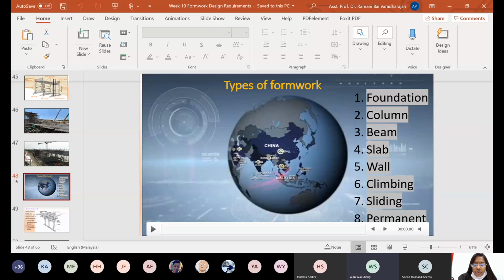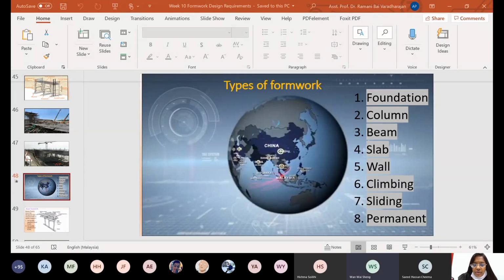Miss, what is the difference between the scaffolding versus the formwork? Between scaffolding and formwork? Formwork is mainly the sides and bottom, mostly the side and bottom is called form. The structure which is forming the column and beam or slab is called formwork. And if you are going to support it, the poles, the pillars, the piers that are going to support these types of forms are called scaffolding. We will have a separate section on scaffolding later.